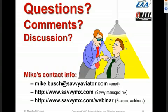Okay, and Nick has a twin Cessna, and he's considering a Plane Power alternator to get better low RPM amperage. Can I replace just one, or would a mismatch be a concern? It depends on the twin Cessna, but for most twin Cessnas with paralleling regulator or paralleling alternators, I would be inclined not to replace just one, because I suspect that you will have problems getting dissimilar alternators to parallel properly with one another.